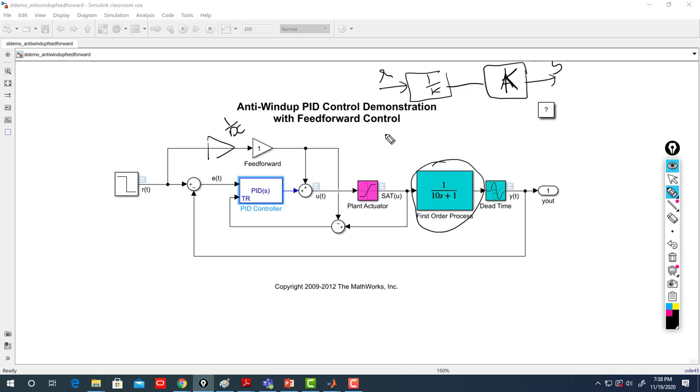And this is important if the transient response is slow and if you have delay, as we saw in the previous dynamic. When I add dynamics here and here, my system becomes a little bit slow. Then why did they put 1? They could put 1 over the DC gain. What is the DC gain of this transfer function? A over Ts plus 1. So T is 10 and A is 1. So that's why 1 over 1 gives you 1.